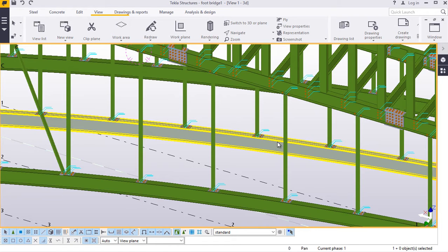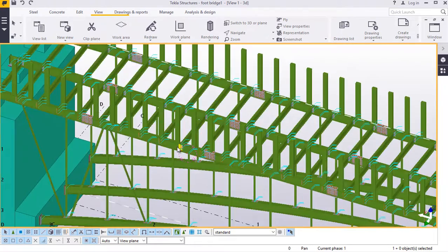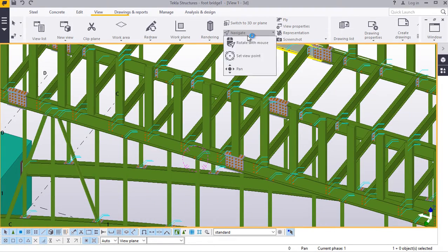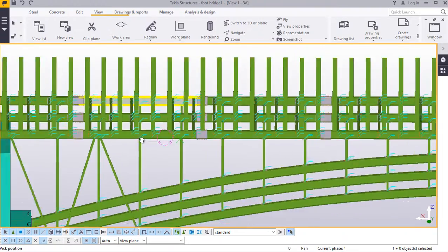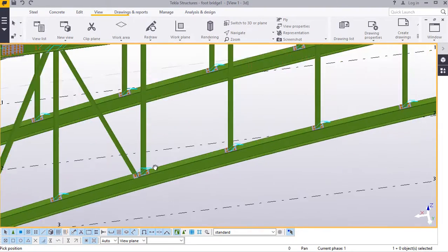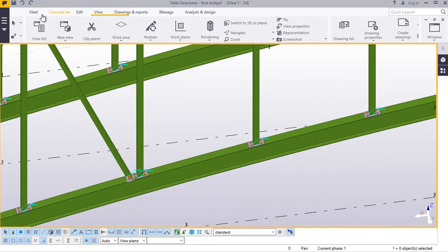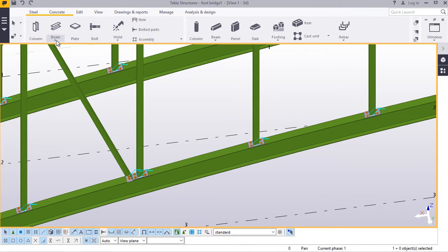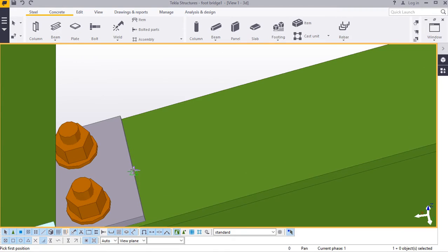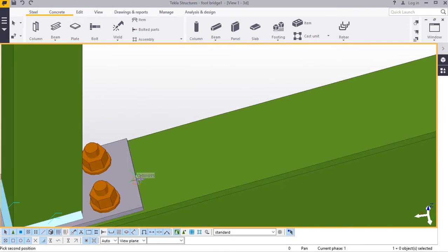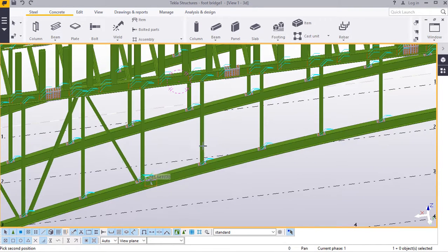Today we are going straight to bracings of the footbridge deck. This one up here. We'll start right off here by placing our bracings. We'll go to steel beam. We'll just snap here the end of this end plate there and go to the very top one.